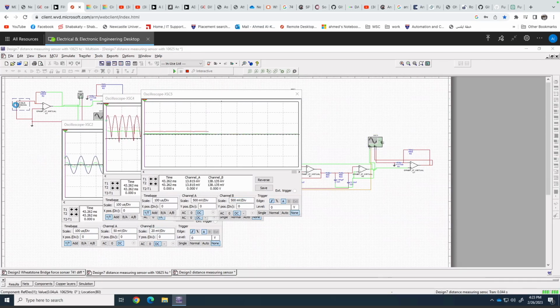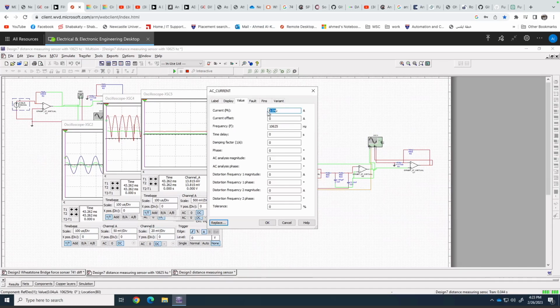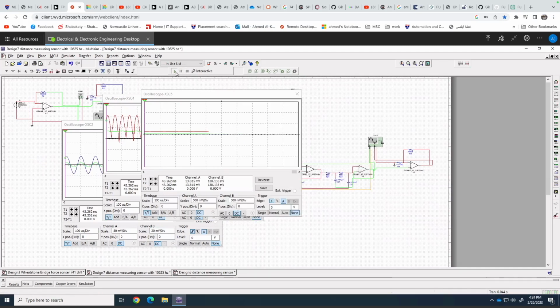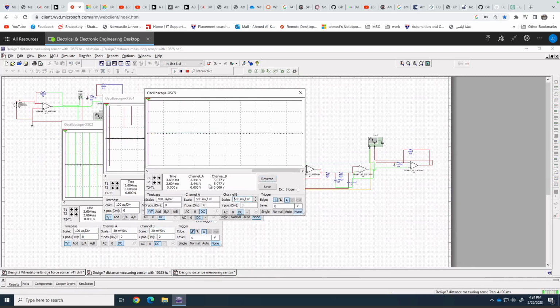millivolt. So if the distance gets closer, for example, the photodiode will generate 300 microampere, and with an offset of, for example, 10 microampere, the offset will be filtered, and you can see here the maximum signal will be 5 volt, which is the full range the Arduino can have for analog to digital conversion, and here it is demonstrated as the signal of the distance sensor. So if it's more than 1 meter, you'll get 103 millivolt, and if it's very close, it will be 5 volt.